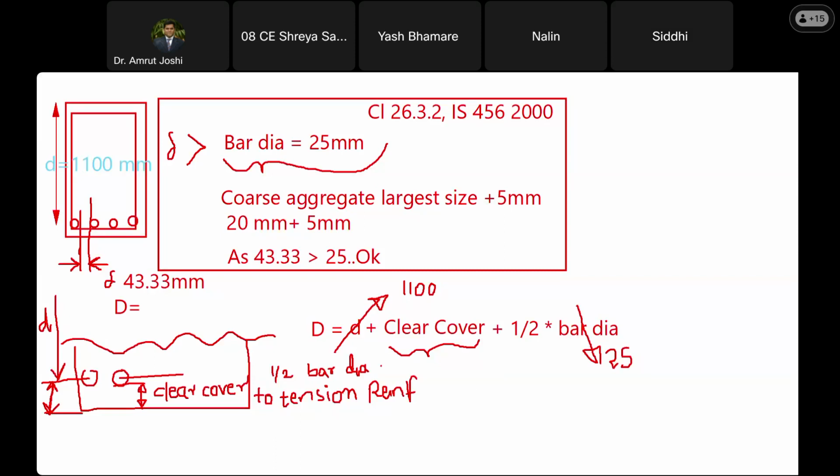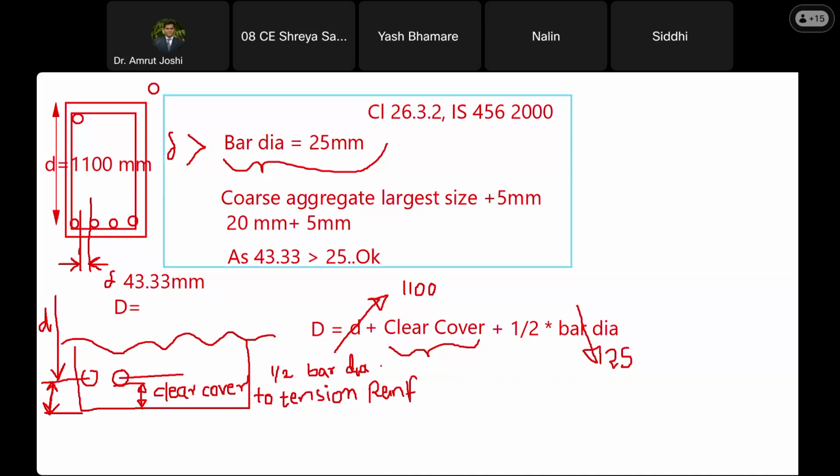Yes. We just now saw this picture, है ना? And on top side also, you are going to have at least 2 bars at the corners of the stirrups. One here, are you with me? Yes, sir. And another here, so that to these 2 bars, I can tie the stirrup. Happy? Yes, sir.